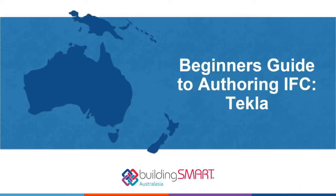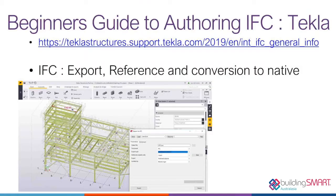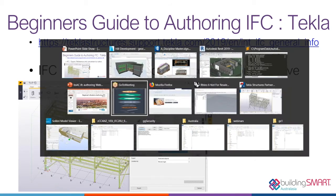The last one that I'm quickly going to touch on is authoring IFC from Tekla. Tekla is a structural detailing application used for concrete and steel structures quite a lot. It's particularly good at fabrication and CNC instructions and shop drawing production. Again, there's a link there if you're looking for some guidance and support from the Tekla Structures website. And it again has sort of three mechanisms for working with IFC as part of that workflow.